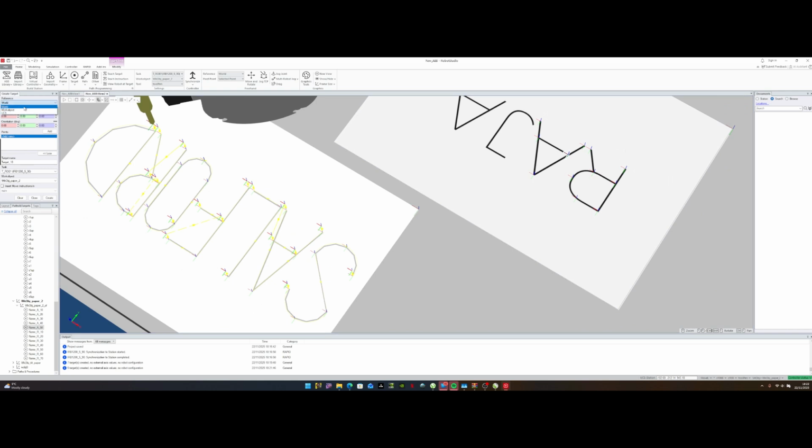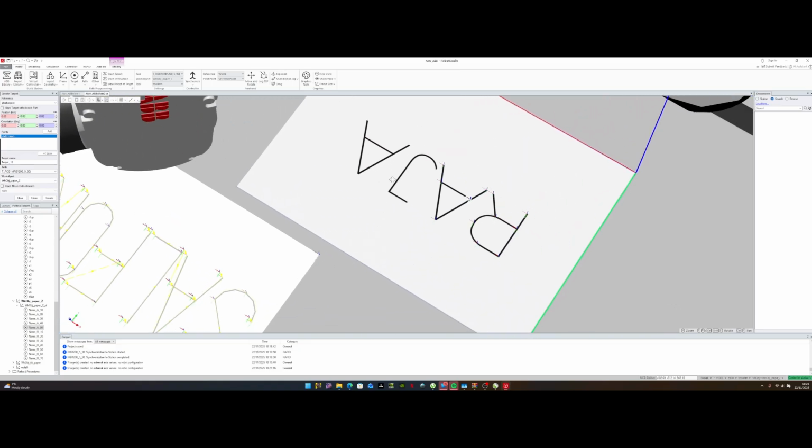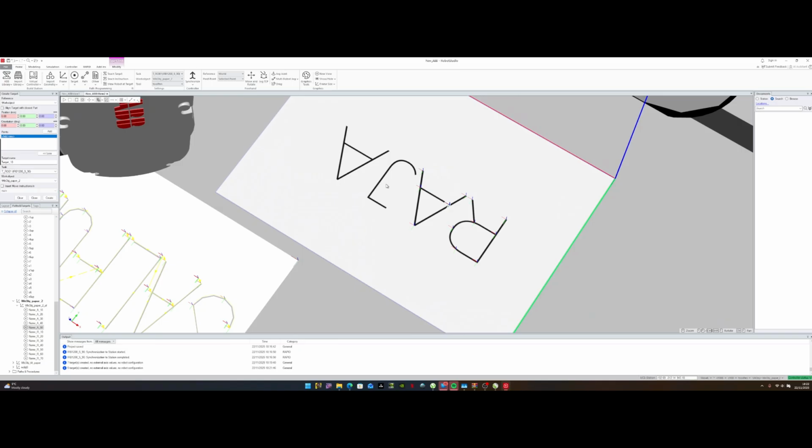So we're going to change the work object reference again, the reference to work objects. Keep doing that. The mistake I already foresee someone making is they forget to do that and they make the target reference world. You know, this is where you need to understand the references. There is the world reference, base link, link 1, link 2, link 3, link 4. All those references are very important. So now let's do the next letter, which is letter J.